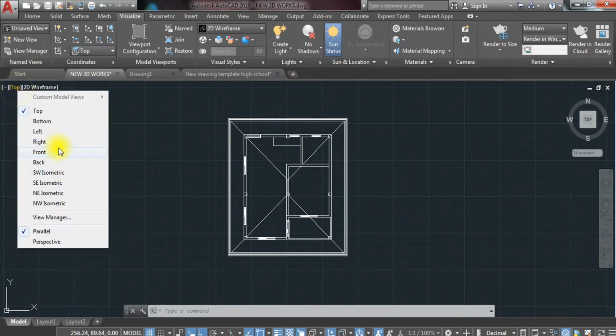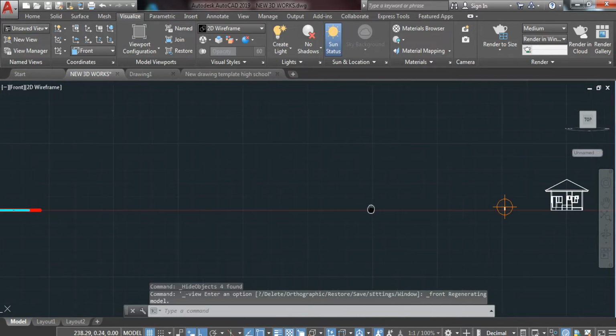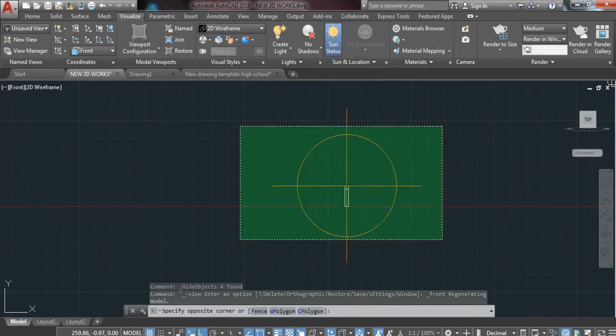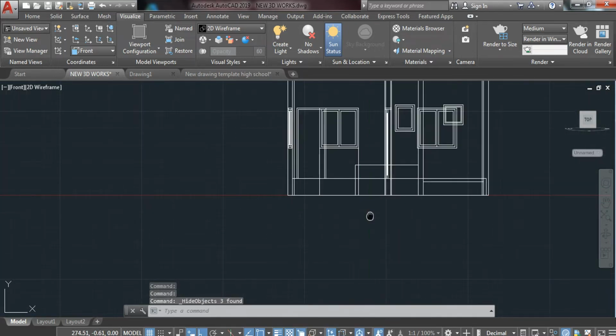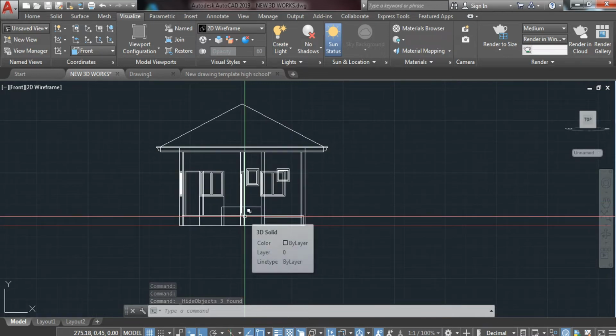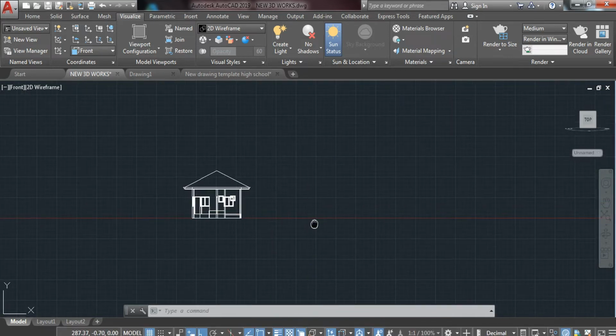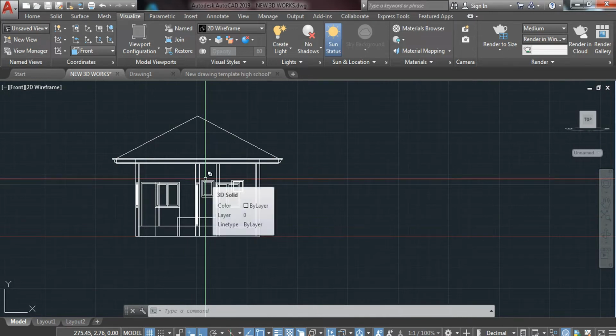Okay? So just click here, front, dito sa top, and then if meron pang naiwan, simply just hide everything. So bakit kailangan natin i-hide? Kasi kapag nag-flat shot tayo ng ating drawing, lalabas po yun sila. Okay? So for your first view, the front, I'm going to type flatshot. Okay? Flatshot. Iba ang flatshot compared sa flatten. Flatshot is just creating another object in a two-dimensional form. Ang flatten naman, ang buong 3D ninyo ay magiging isang flat surface only. Which we do not want to happen.